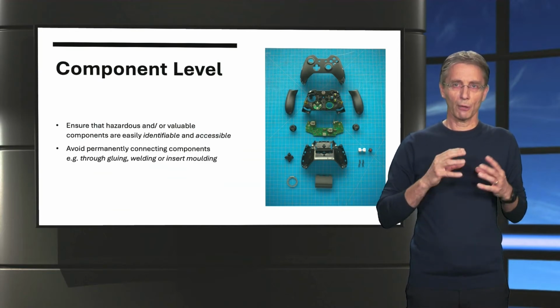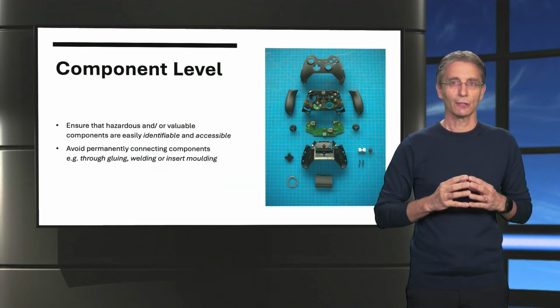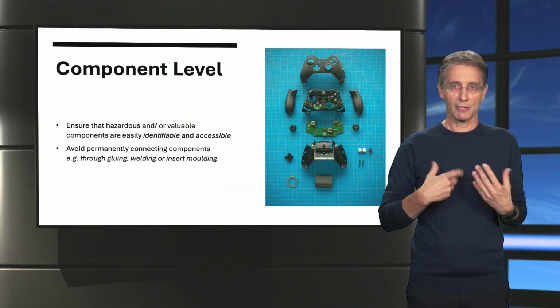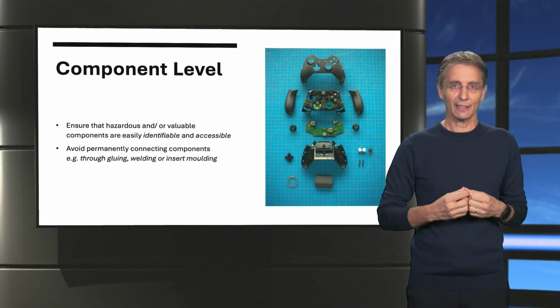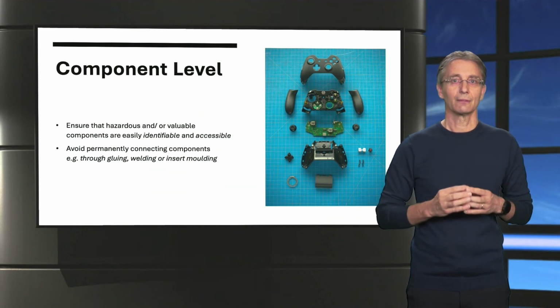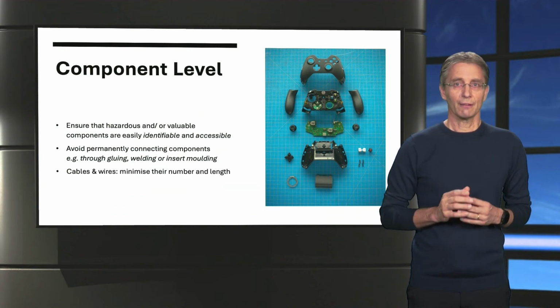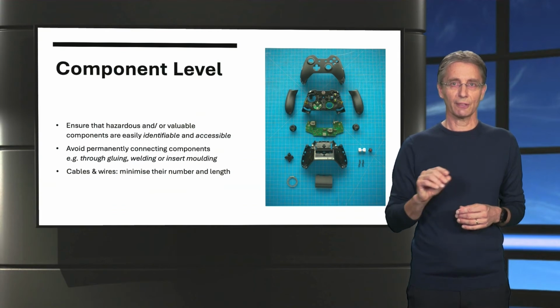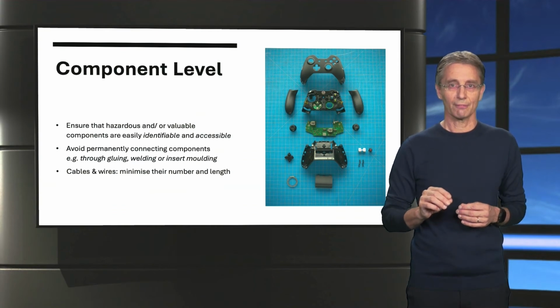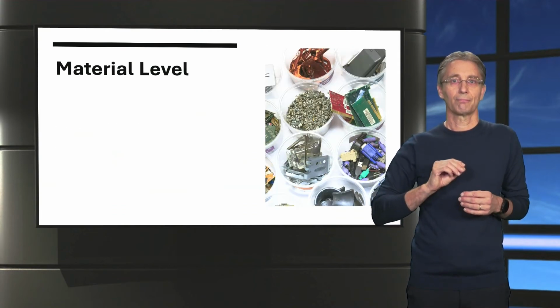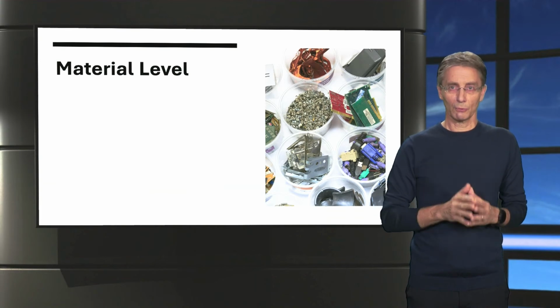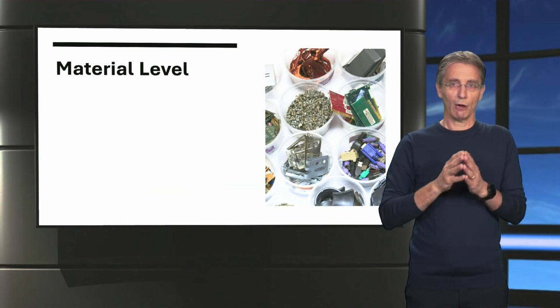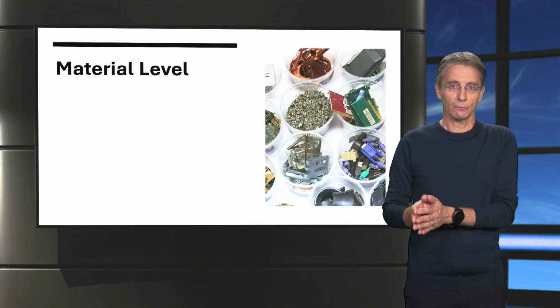Always avoid permanently fixing these components to other parts by, for instance, gluing, welding, or insert molding. Finally, whenever you need to use cables and wires in your product, try to limit their total number and length. From the component level, we now move on to the material level.